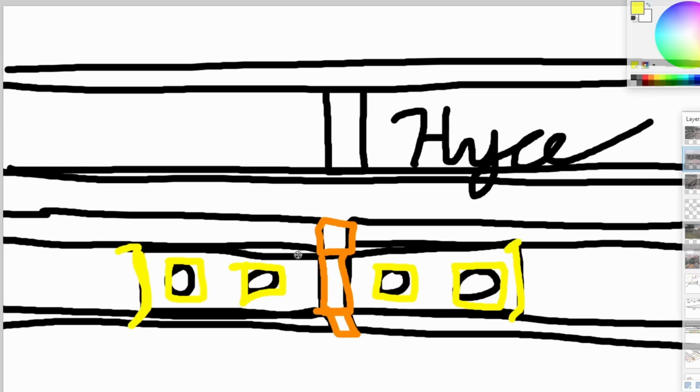And later, we ended up getting continuously welded rail, where we would weld the joints using thermite in a cool, flashy way to actually affix our rails so that we get a continuous head of rail so that the wheels never get the clickety-clack over the joints as they go across. But that said, we still do have these orange insulated joints for signaling applications, common across the railroad.